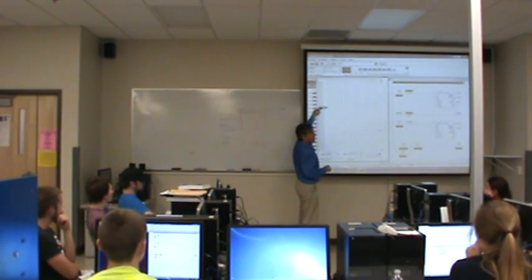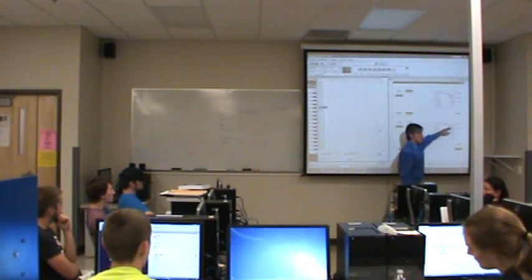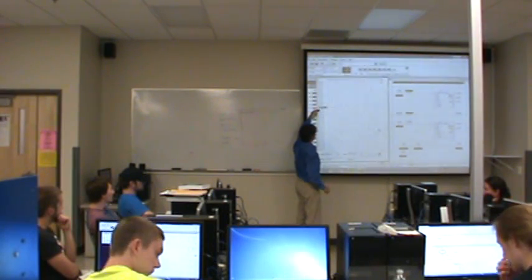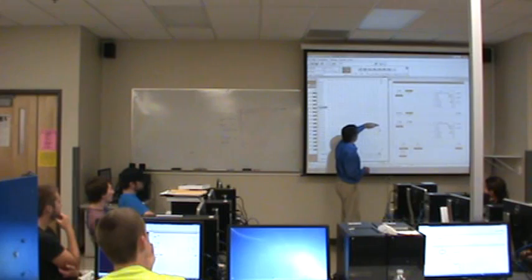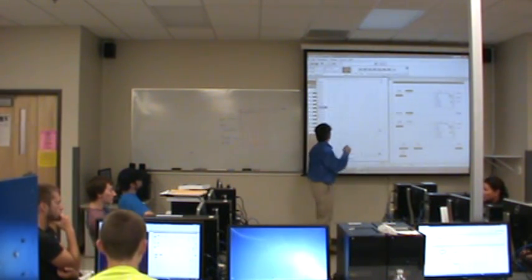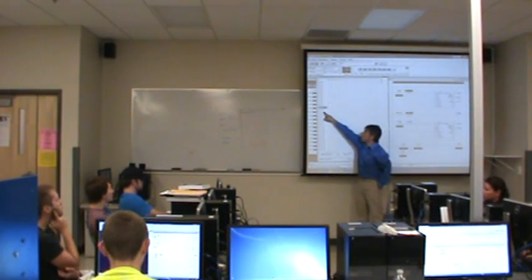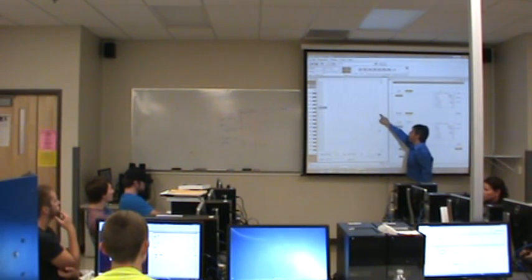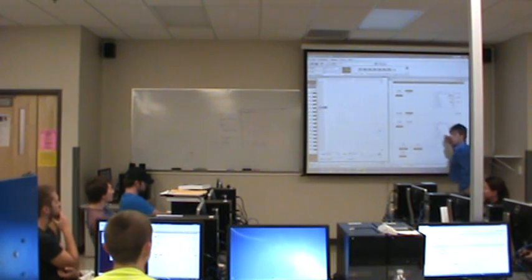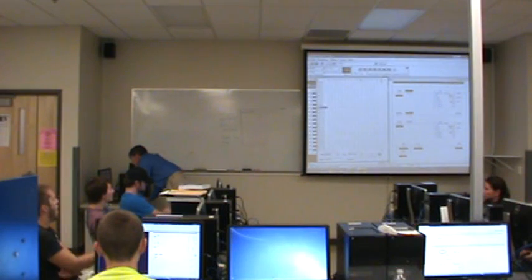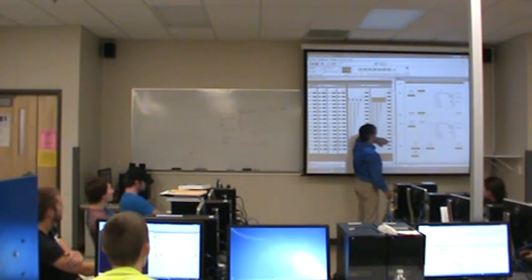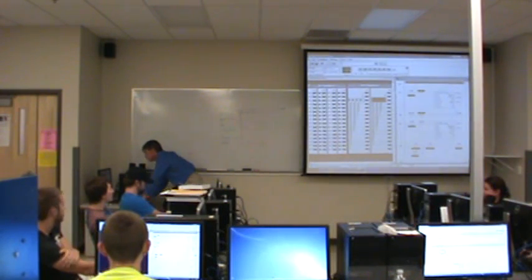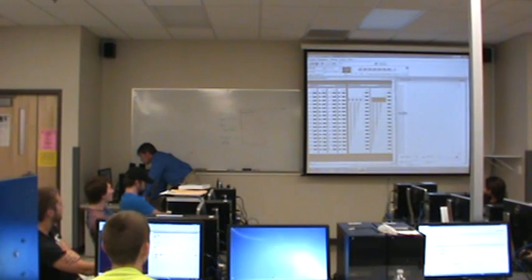Essentially, the list starts at the address after the one you reference. Okay? So what you really care about is the address just beyond the address that you type in there. So we're interested in 11 through 8 steps. So 1, 2, 3, 4, 5, 6, 7, 8. All of these are my list. And these are what I've put in that I wanted to output. So in the first step, what it's going to do is it's going to copy B3:11. It's going to copy all of these bits, all 16 of them, and it's going to paste them into output 6. Okay, now output 6, if you look in this particular simulator, is this output right here. So it's going to copy all zeros and their 1, which is right here, to output 6.